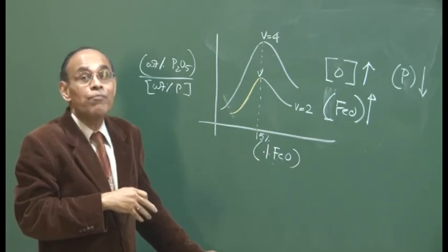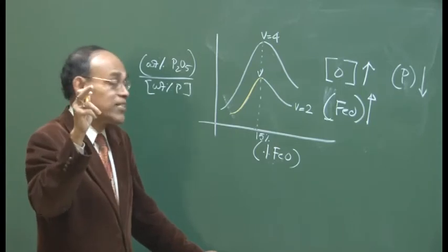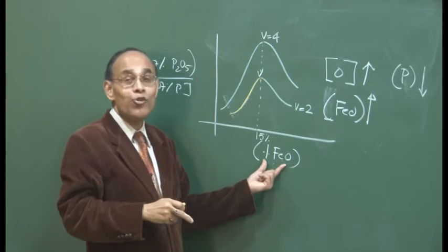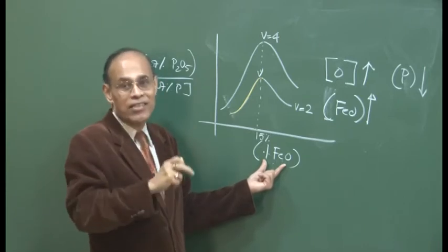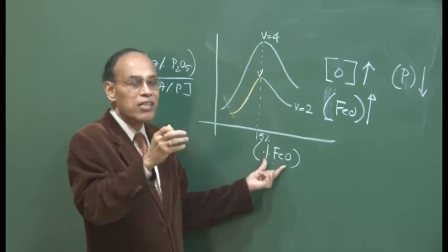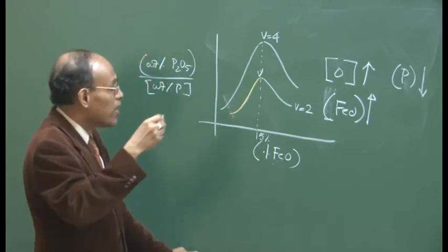Therefore, endpoint control has been given so much emphasis in modern day steelmaking, such that there is not an excess amount of FeO. Controlling FeO in the slag is a great art as far as oxygen steelmaking is concerned, and this will to a large extent give rise to the correct kind of temperature towards the end of the blow.